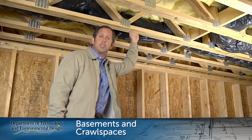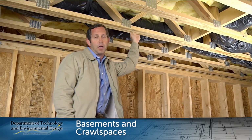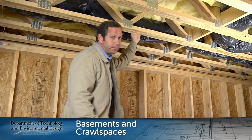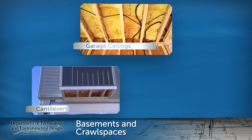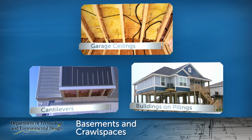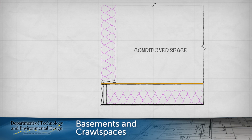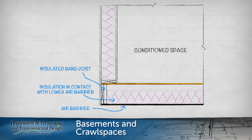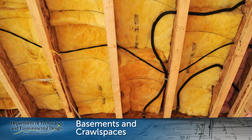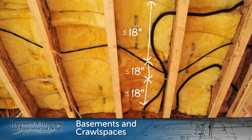Floor insulation must be installed to maintain permanent contact with the underside of the subfloor decking. But there is an exception. That is, garage ceilings, cantilevers, or buildings on pilings with an enclosed floor cavity. In this case, the insulation may contact the lower air barrier if the band is insulated. Of course, support wires and other devices that hold the floor insulation in place must be no more than 18 inches apart and within 6 inches of each end.